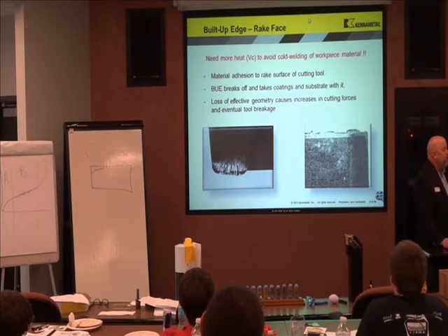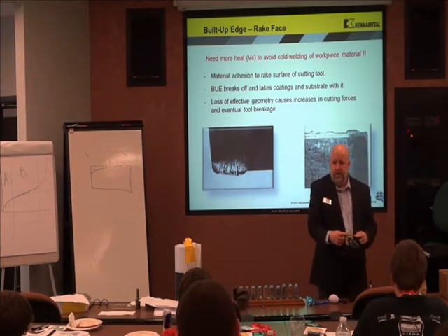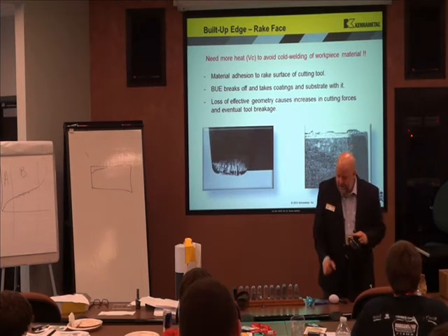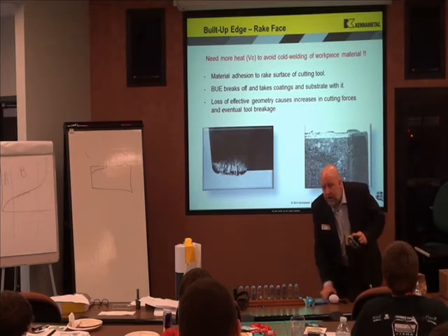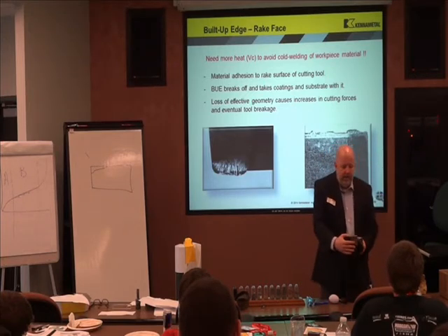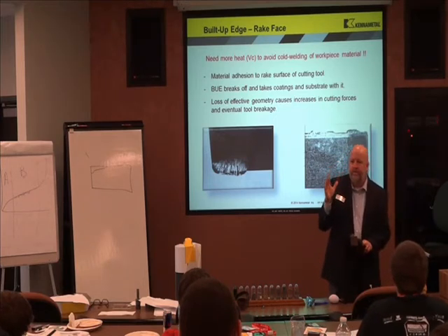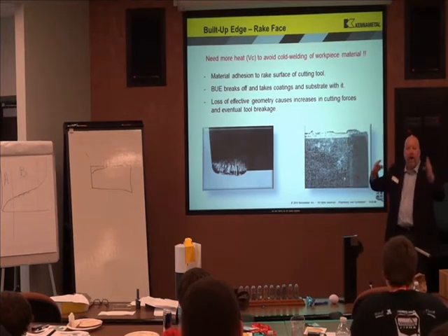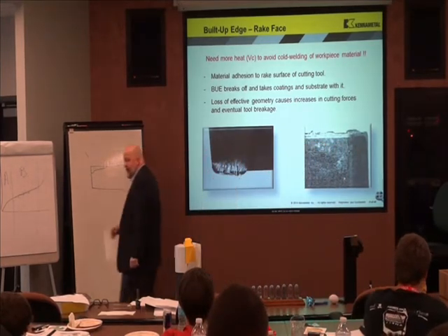The other thing you need to remember when you're getting built-up edge on your cutting tool: if I flip it over, I better first take this insert, this edge that has the built-up edge on it, and rub it on a piece of sandpaper, clean it off, before I flip it over and put it back in. Because if that built-up edge hits my seat before the mounting surface, my insert's going to rock. Okay, so for built-up edge, it's pretty simple. I also may want, would I want more negative? Remember my negative and positive earlier?